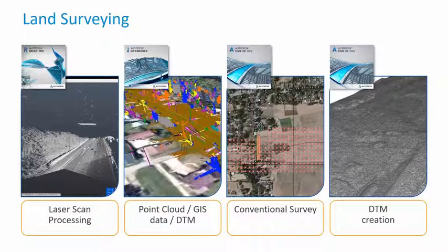And also it's not mentioned here, but the data which you created in GIS you can bring over to Civil 3D as well. So later on for detailed design you have all available information. Maybe what I should mention is that Civil 3D is based on Map 3D, so all functionality of Map 3D is inside of Civil 3D, which means that Map 3D also has functionality to bring GIS data in, not using InfraWorks, for example, but directly using what we call FDO providers.